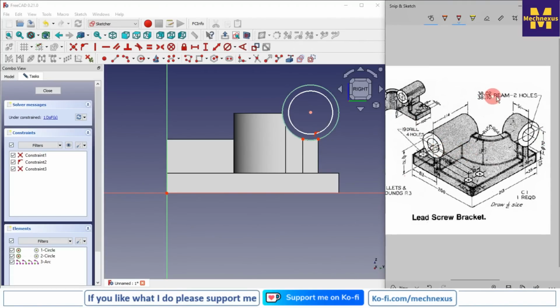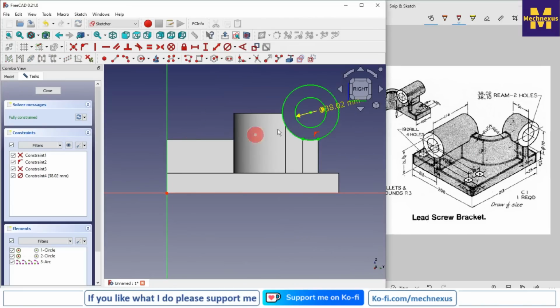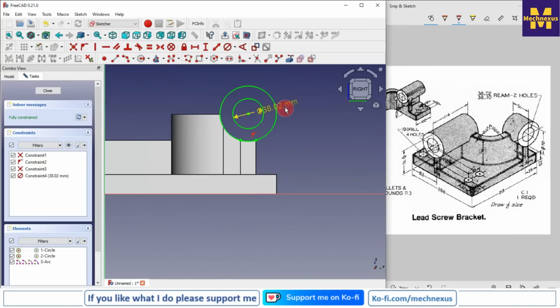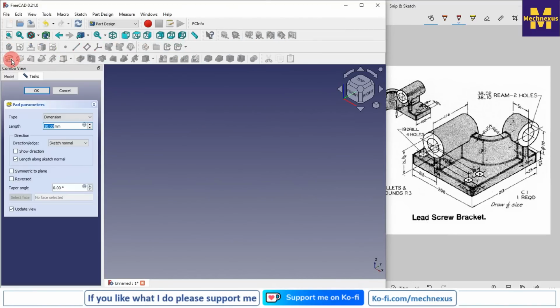So we can see that rim 2 holes 38.02, so we will take the maximum value, which is a 38.02. Select on diameter 38.02. Now I will move my dimensions and I will close it, select the sketch, click on the pad option,